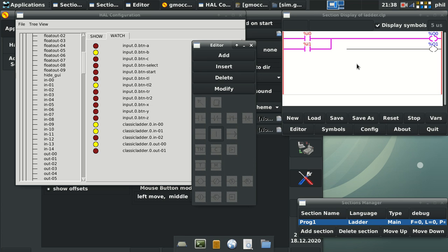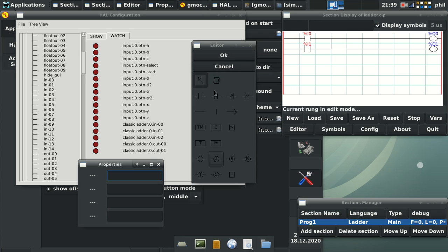Both of the buttons can be hit together, which can create some issues in certain cases with PLC. In that case, you would use an exclusive OR or an XOR statement, which would just include shutoffs for each section of the ladder. I'll show you. I'll see if I can do this on the fly. I'm going to call this input 0. Call this input 1.